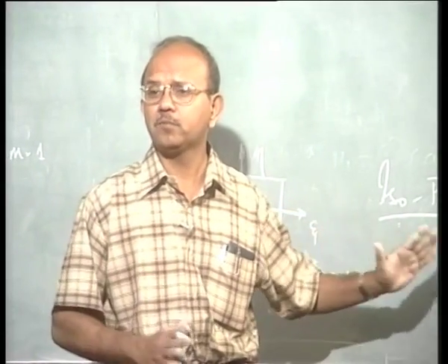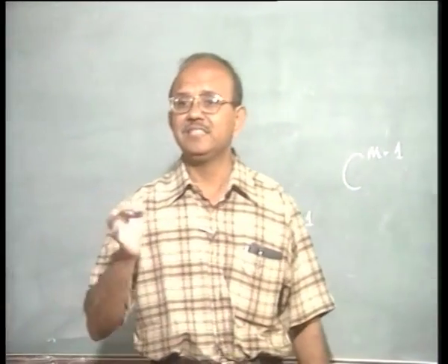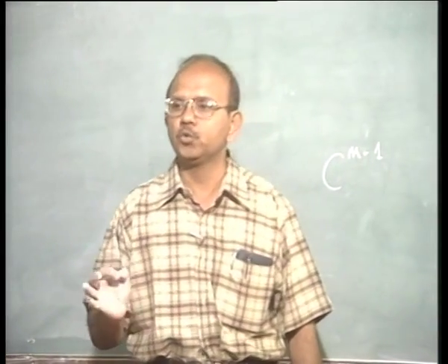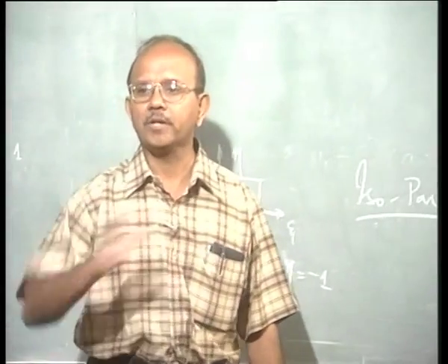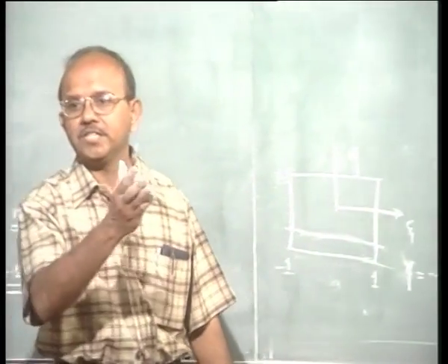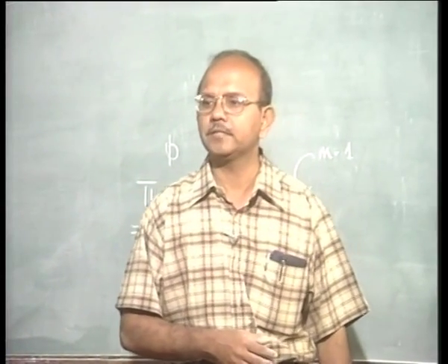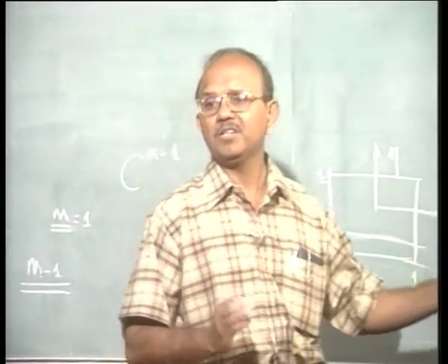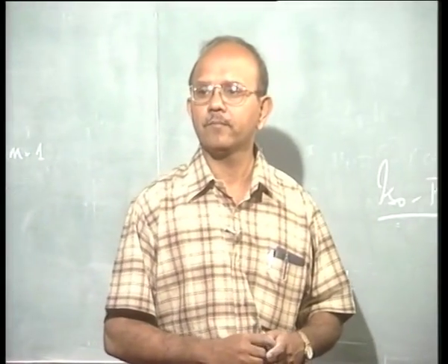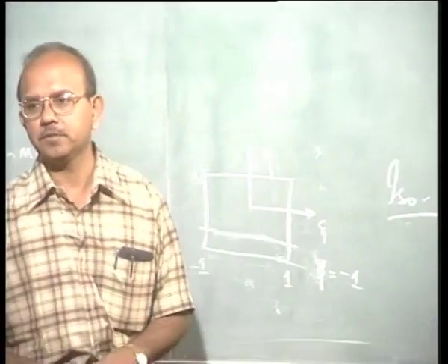The whole thing was possible by the isoparametric concept, and it is the most important element used in commercial packages. Whatever elements you have been seeing, the results of which you have seen in the past few days, have been possible because of this concept. Hence, it is important that we understand isoparametric elements.